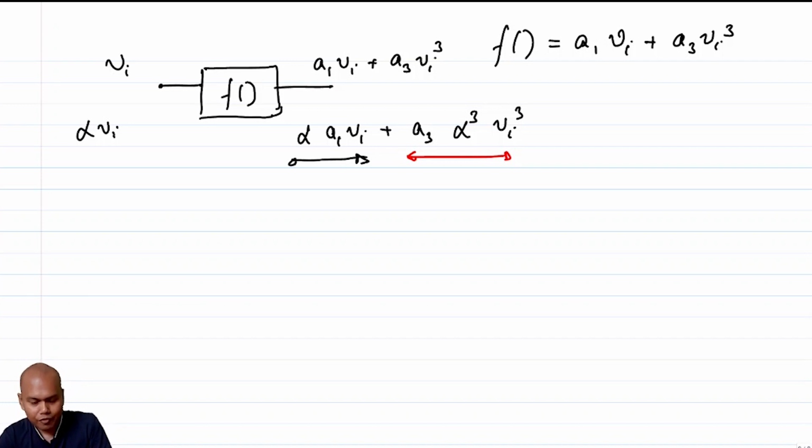And that should be evident by now, because the metrics of IIP3 and IIP2 and all those things essentially leverage this fact that the distortion terms increase at a faster rate with respect to the fundamental as the input amplitude also increases, right? So now, given that we have this observation, is there something that we can do, at least mathematically, to get rid of the distortion term?